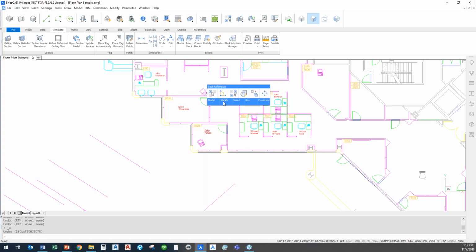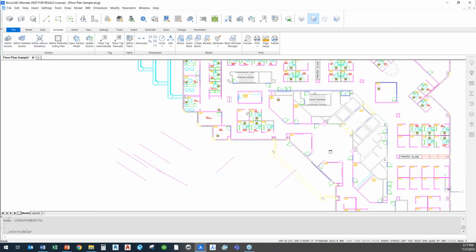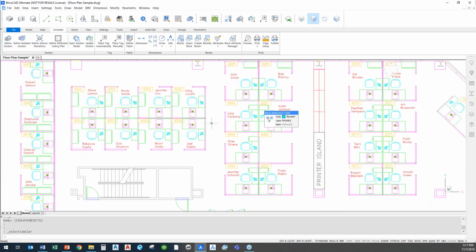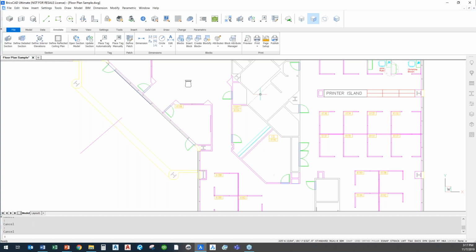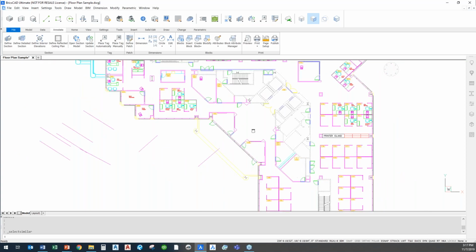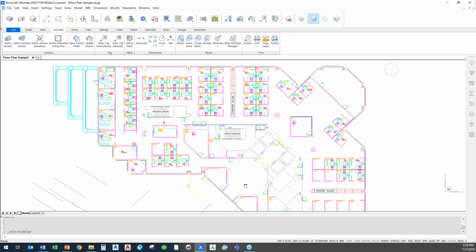The other thing that you can do here, you can go back and you can hide and unisolate, or you can actually select similar. Just like that, I can select all of the similar. I see it selected every single computer for me in the entire setup. Same thing, it'll select walls, all the walls, lines that are all in the same layer, and it just repeats that last command. I can very quickly, all throughout my entire drawing, find similar items that are of the same type and the same layer, all using the quad tool.